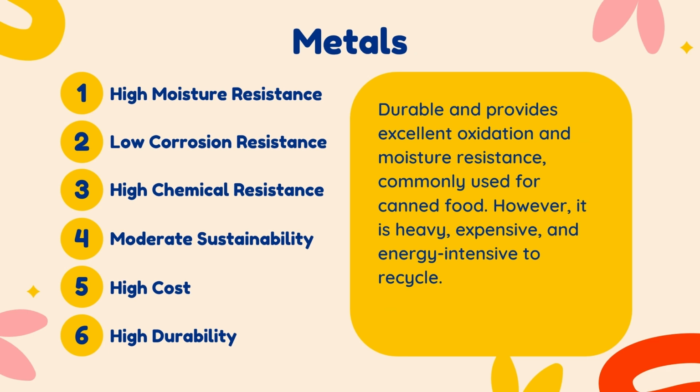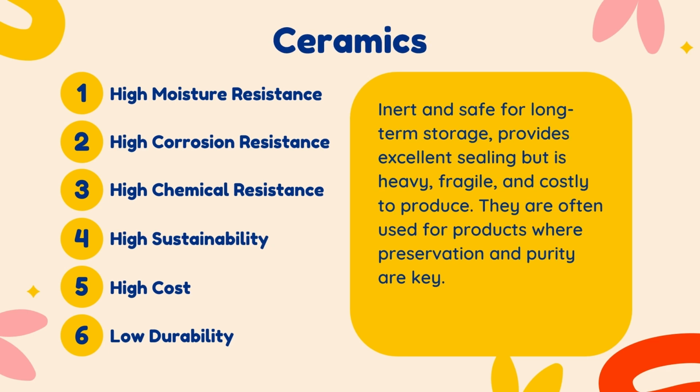Next, metals are durable and provide excellent oxidation and moisture resistance, commonly used for canned food. However, they are heavy, expensive, and energy-intensive to recycle. Next, ceramics such as glass are inert and safe for long-term storage, and provide excellent sealing but are heavy, fragile, and costly to produce. They are often used for products where preservation and purity are key.